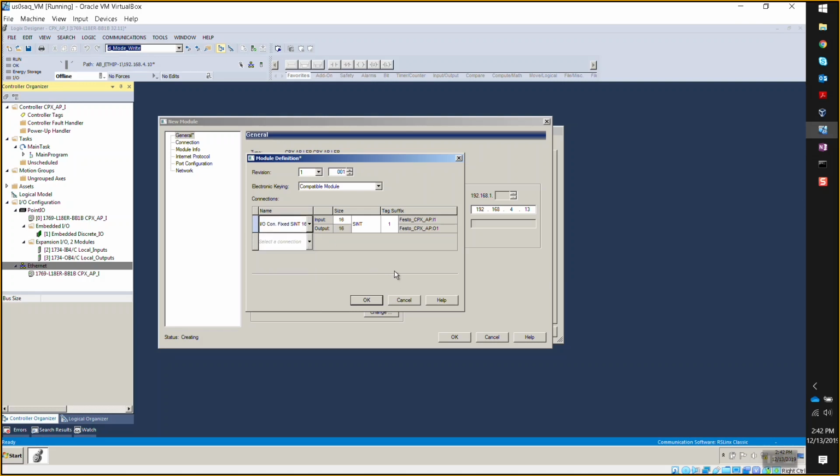Okay, great. If you want diagnostics again, you can hit the pull down below, and now you could add either status only or diagnostic data, which would be status and module. So these are the global and yeah. So which one will be the global? So just the global is status only. Okay, and if I wanted per module diagnostics, then it would be diagnostic data. Yeah. Okay, so which one do you usually recommend going with? Well, why don't you do status only in this case? Okay, so the global. Yeah, and it should be 12 bytes, and it is.